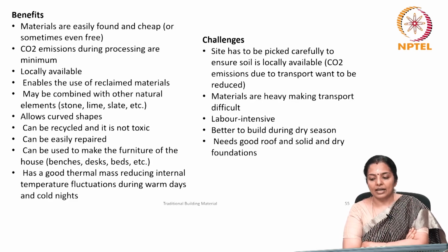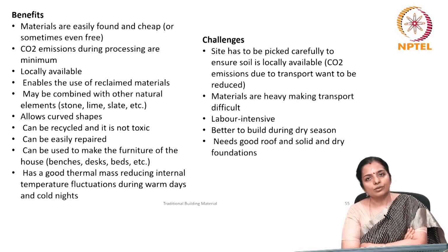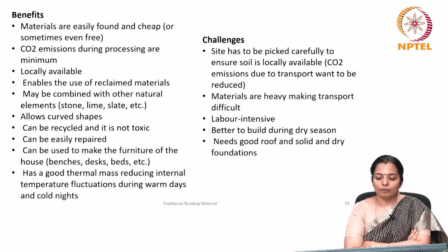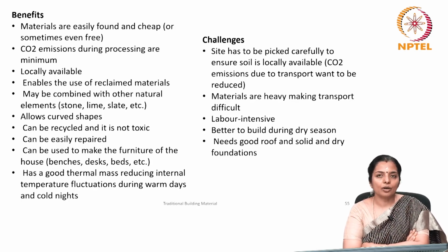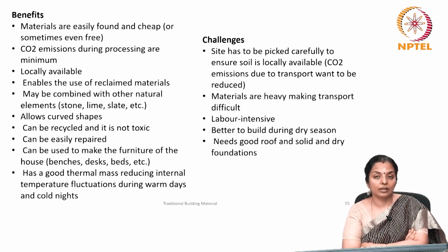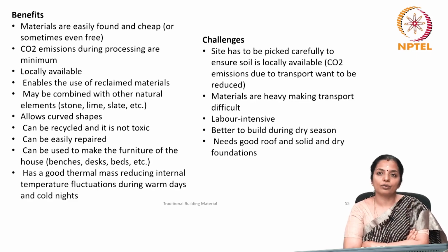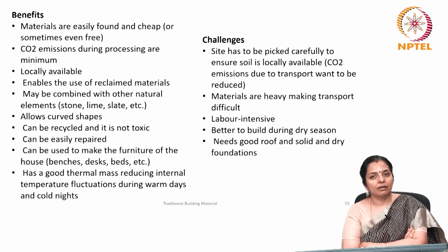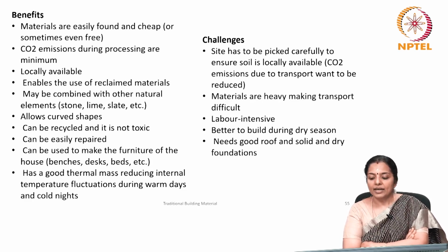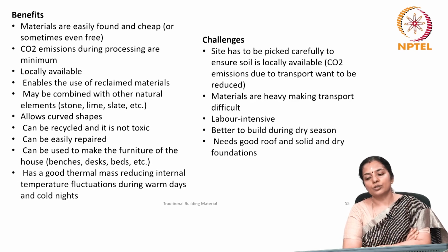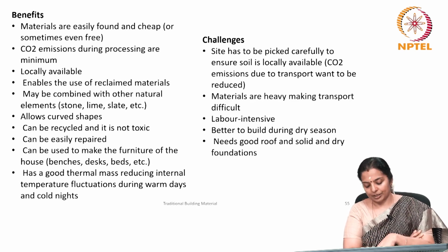The materials are heavy, making transport difficult, but that is also the case with brick or stone. It's a labor intensive material, no doubt, because if you are going to make the blocks manually, you will need a lot of labor, which is a challenge but is a good opportunity for the local economy to flourish. It is better to build during the dry season and it needs a good roof and a solid and dry foundation.